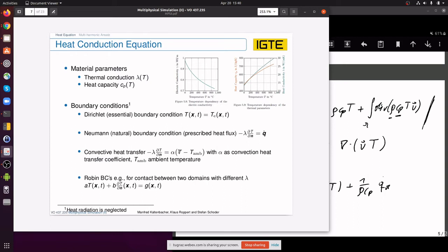This heat flux depends on the temperature difference between the solution quantity, the temperature at the boundary where we apply the heat transfer condition, and the surrounding, maybe air, temperature. So we have to prescribe something that we do not know yet. This will be assembled into our system and handled that way.